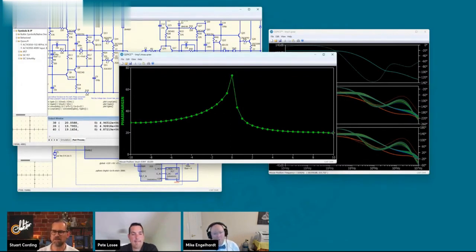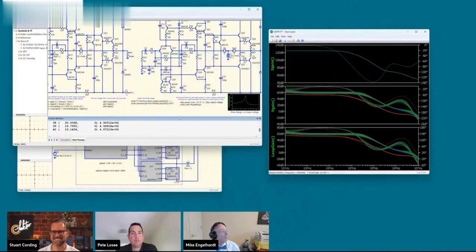And you know, if you've played with audio amplifiers, you've certainly seen audio amplifiers that have a nice sine wave till they get to the positive rail, then they oscillate, then they get away from the positive rail, they stop oscillating. You've seen amps do that, and this lets you quantify it very, very well. In fact, if you really zoom into this central region, you'll see that there's a lot of structure in exactly how the high side and low side varies. The phase margin varies wildly within just tens of millivolts of the output being centered.